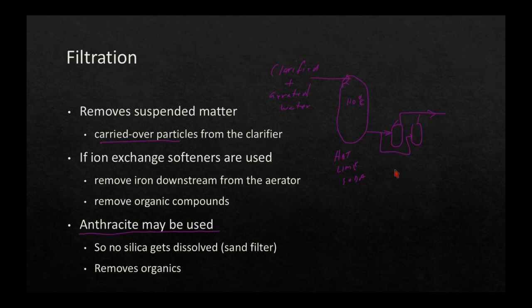If those filters contain silica sand, okay, so sand is SiO2, well, we've gone to great pains with our hot lime soda softener to remove silica. And then we take that hot water and put it through silica sand filters.